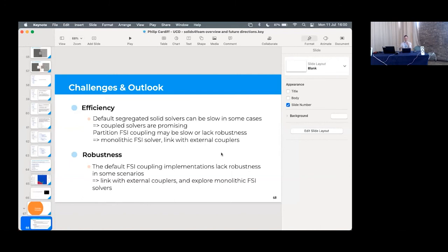With a vertex-centered method, you have a point right on the interface, so you don't have to do anything special. You add a contribution from the left and the right, and that's it. In cell-centered, you have a jump like in multi-phase, so you have to do something special with the gradients. So there are some conveniences in that regard. The inconvenient thing is everything in OpenFOAM is written for cell-centered, so you have to rewrite everything yourself if you want to get a gradient.